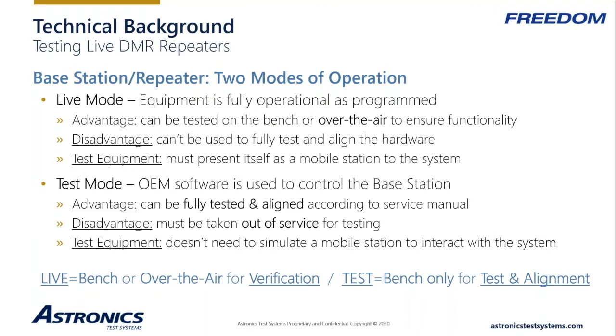And that's what the 8100 will do. It will basically mimic that wake-up sequence to, let's say, lift up the communications or enable the communications with the repeater again. The test equipment in this case has to be able to generate that sequence. And in this mode, the repeater can be tested while directly connected to the test equipment. It could be on the bench or it could be over the air.